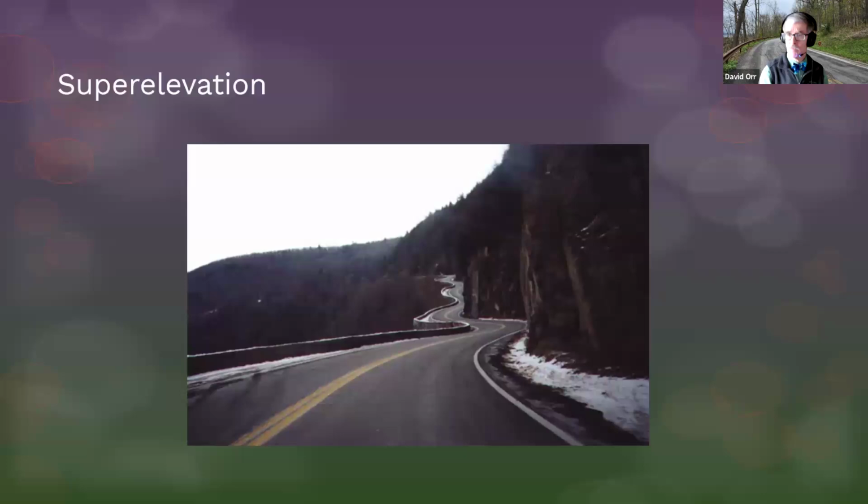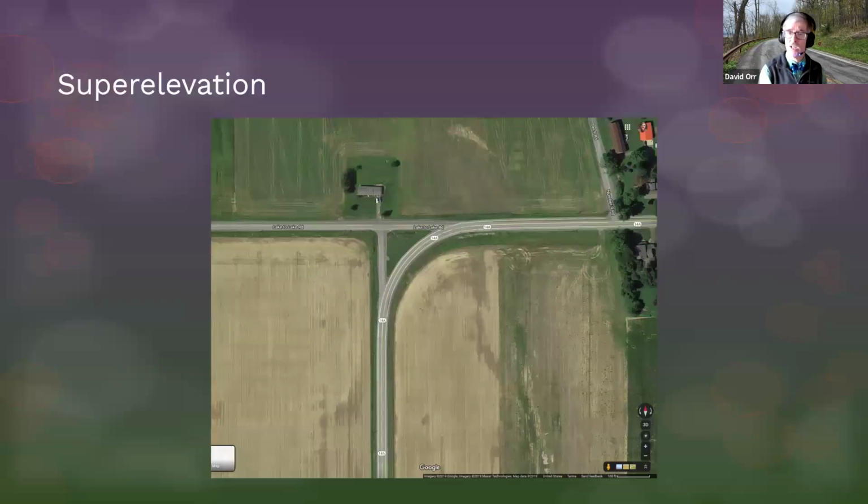The bigger issue I worry about with super elevation isn't a road like this. It's a road like this, like we saw just before. Let's say you wanted to put a nice consistent super elevation all the way around that corner. Really good idea. However, how do you transition that to the intersecting roadway? Well, one of the other reasons we like to bring the roadways in at a nice 90-degree angle is then you can actually have a straight transition with a horizontal curve to bring that roadway in properly and still have the nice super going all the way around the corner. Because if it's too differential, you're going to throw your ball bank off, and you're going to have issues with safety when that happens. So again, super elevation is something you may want to think about.